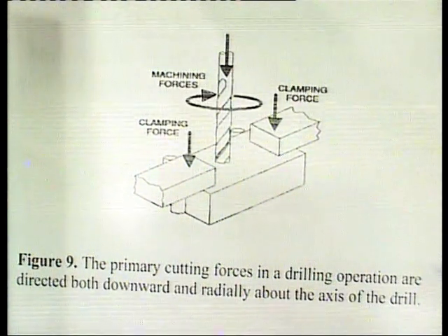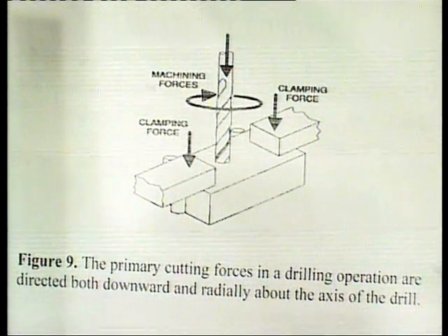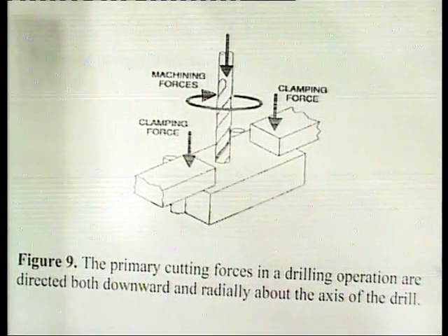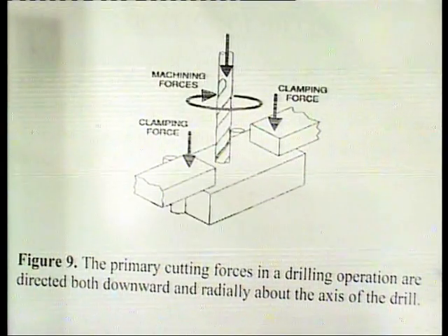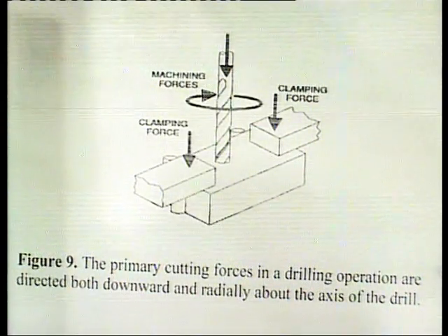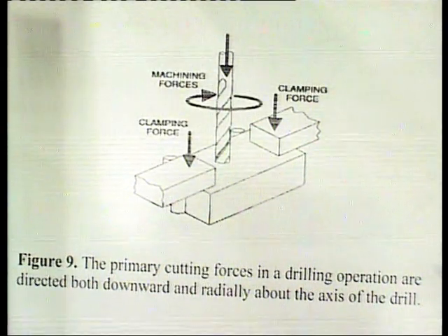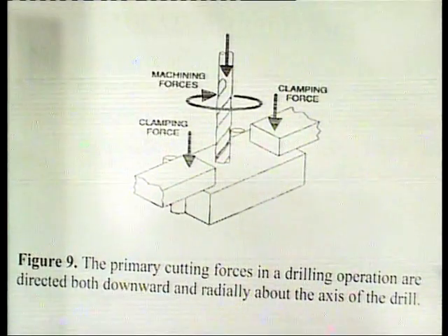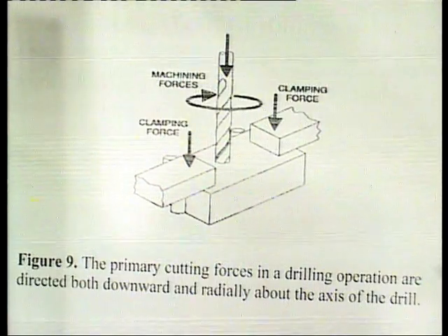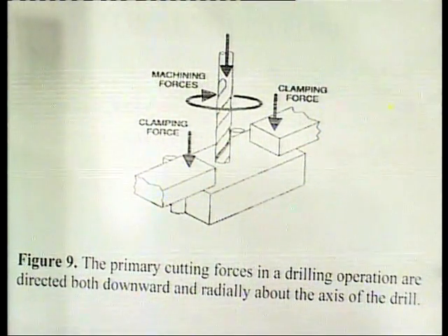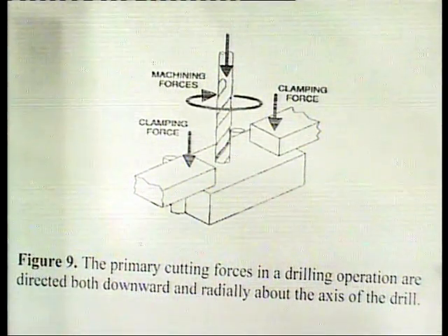The only real force exerted on the clamp occurs when the drill breaks through the opposite side of the workpiece. The machining forces acting on a correctly designed work holder actually help hold the workpiece.